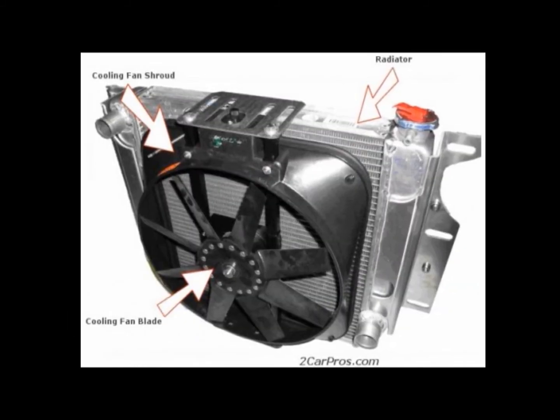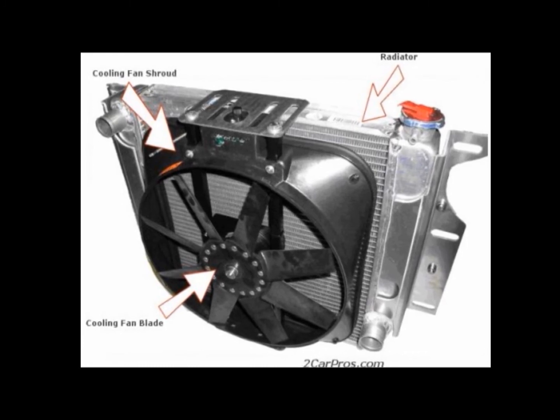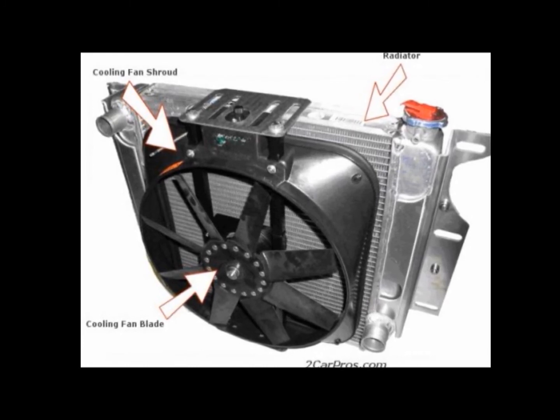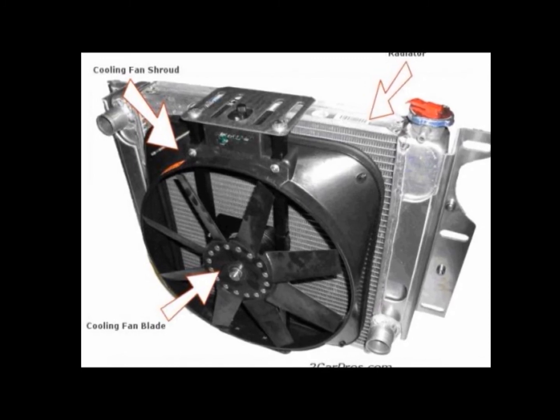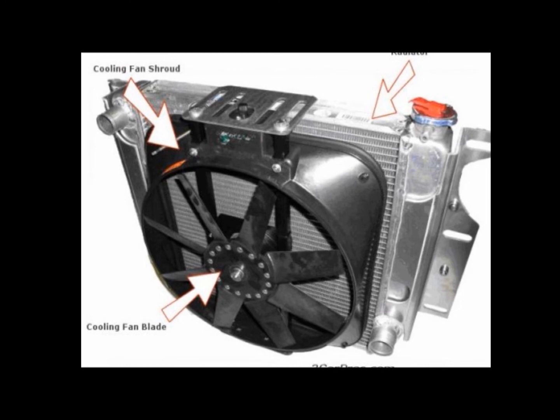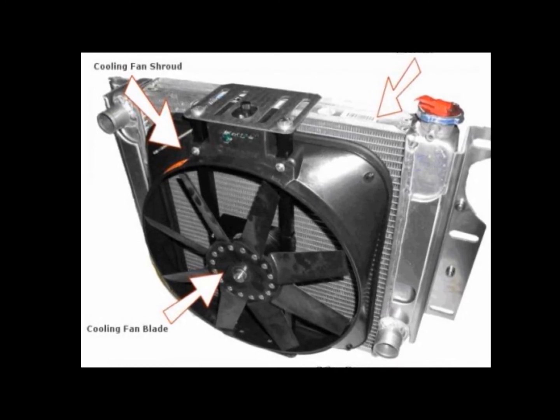This coolant is usually water-based with the addition of glycols to prevent freezing and other additives to limit corrosion, erosion, and cavitation, but may also be oil. The first engine used thermosiphon to circulate the coolant. However, nowadays all engines but the smallest ones use a pump.